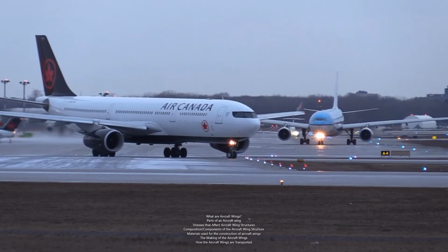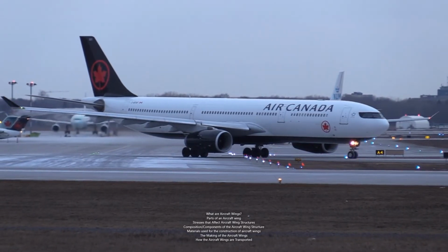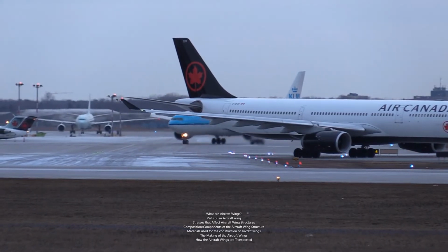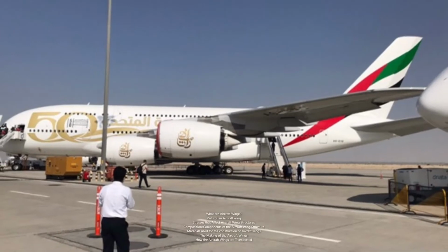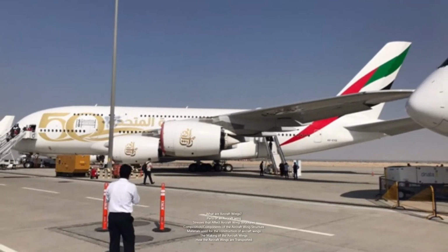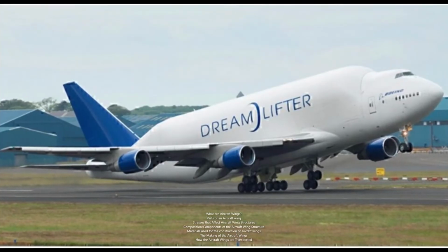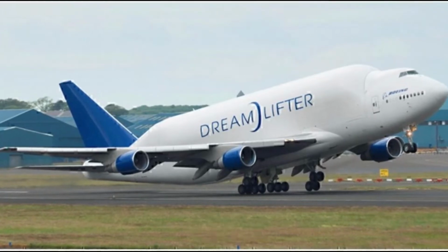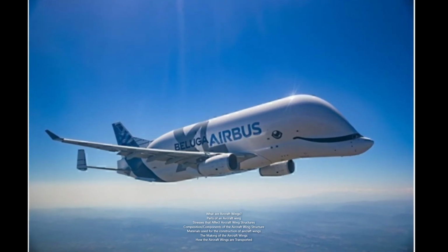Aircraft wings are required to have more aerodynamic efficiency than any other part of the aircraft. This means they must be able to generate far more lift than they do drag. Thus great care is taken to ensure a smooth outer structure of the wing as well as a very lightweight structure. Although longer wings come with some aerodynamic benefits, the wing shouldn't be too long because of the additional weight it would bring and consequently, fuel burn. If the wing must be longer, the material used to construct the wings must be lighter. There are also practical reasons for length restrictions such as landing in airports or parking in hangars.